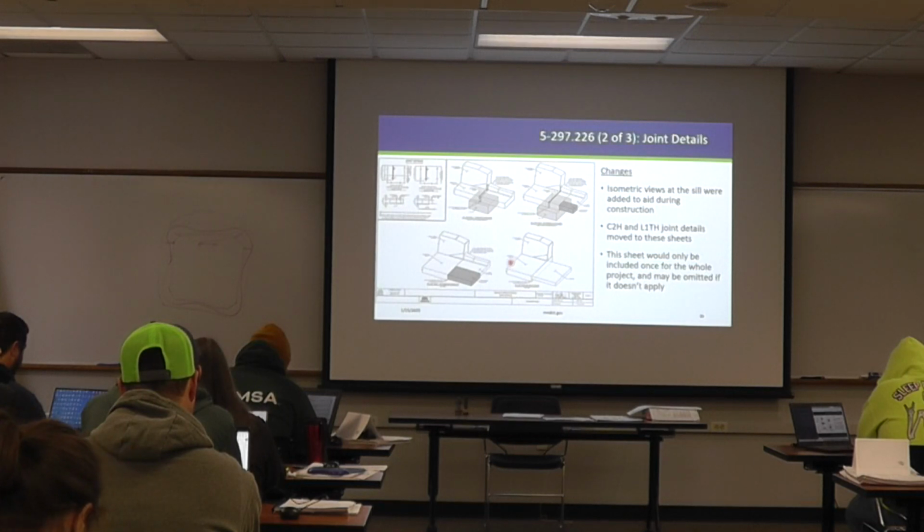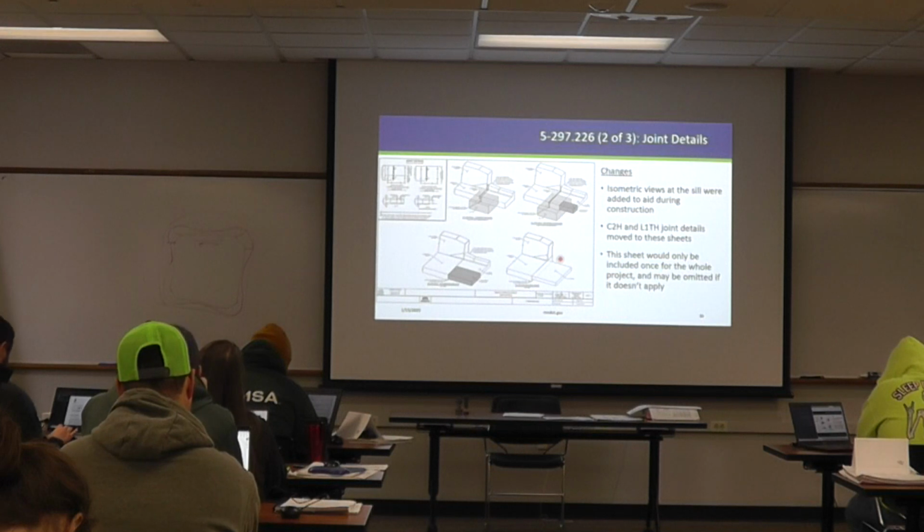Okay. So there is this other option I'm showing down here. This is really only for local roads. Local roads might not have the curb transition coming up to it, if it's a low speed, for example, that might be an option. So you might see that if you're on more state aid projects, but typically MnDOT would not have this detail.